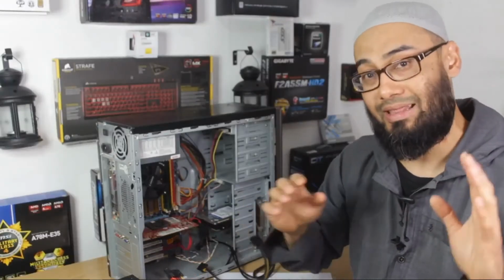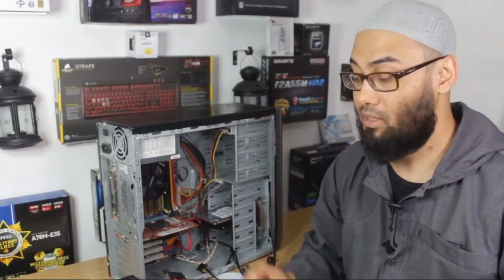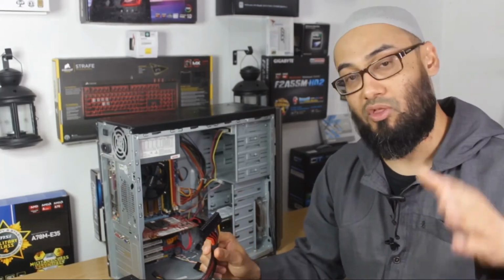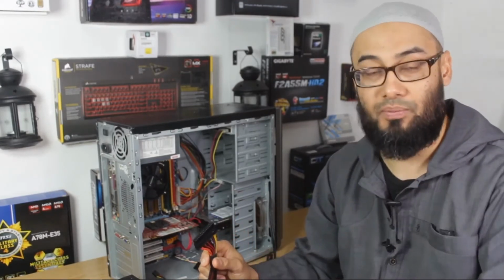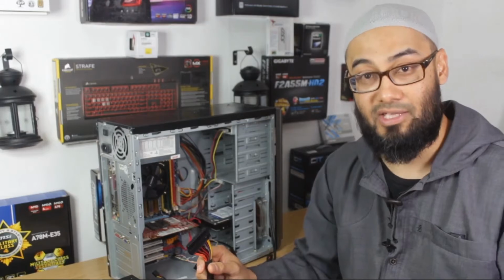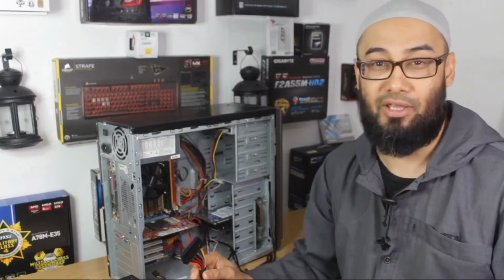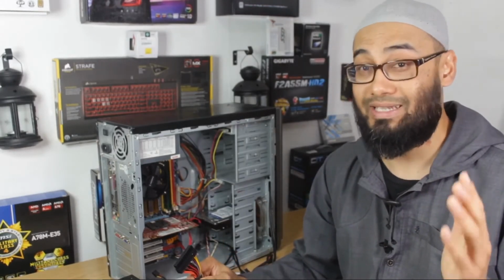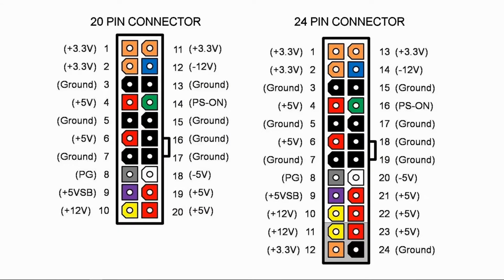What I did not show in that test, and what I did not explain, was that this test will only show whether the power supply is turning on or not, but if it turns on, it will not test whether it's delivering the correct voltage, and that is an advanced troubleshoot test that you need to do. According to many, using a multimeter to test DC voltage is not a conclusive test, as the PSU needs to be tested under load, which requires other equipment I do not currently have. If you do and you possess the know-how, hit me up for a collab, or else you need to wait for when I can actually do a proper test.